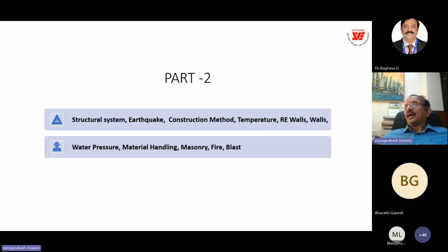This is our observation. I don't have any research to support my claim, but I observed this in at least 4 or 5 projects, particularly flat slabs and normal two-way slabs. Every time we get an alarming call from the client, we go inspect and find that the cracks are only shrinkage cracks, because we verify the depth of the crack and all.